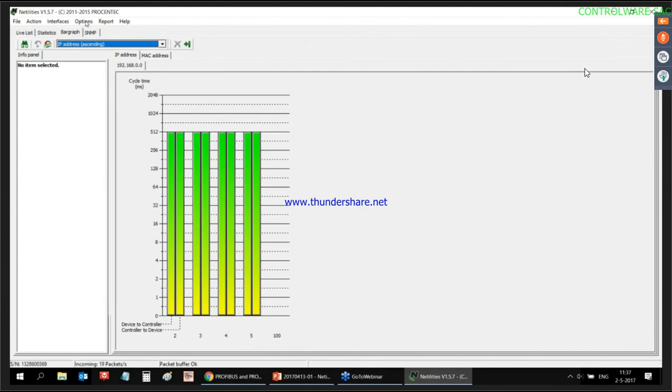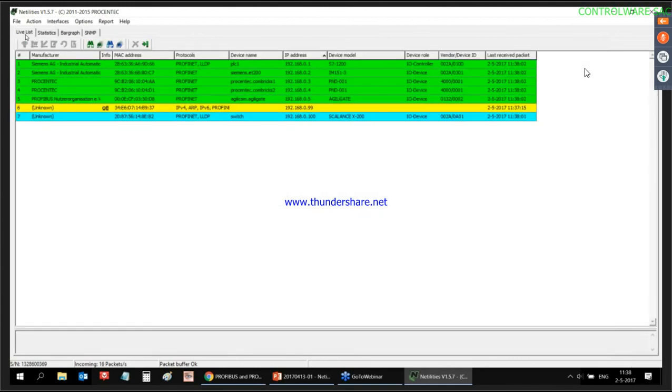What we saw around the main issues is some devices, mostly cheap companies or rebrands, do not support all the features that Profinet is capable of. Like SNMP is mandatory only in the latest Profinet version, which was released 2 years ago, something like that. So a lot of devices around are still in Profinet version 2.2, I think, which says it's better to use SNMP, but it's not mandatory. So when you see that a device is not sending you SNMP data, it's because it's not supporting it.